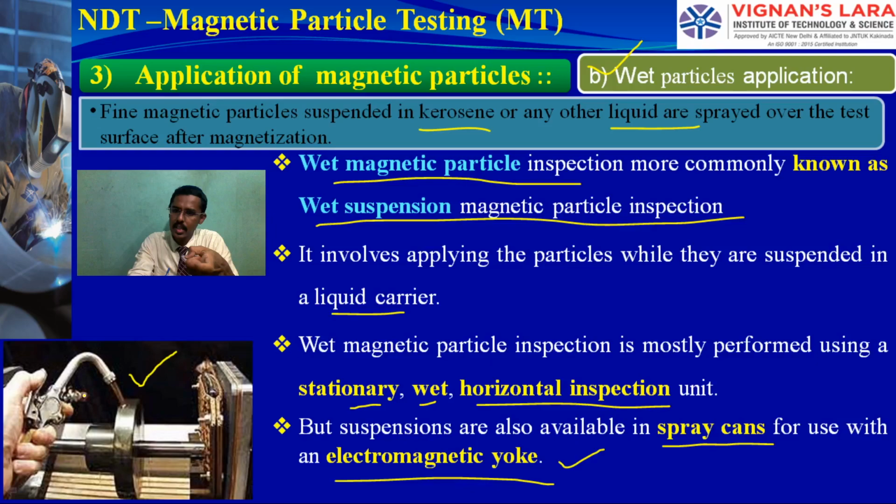The liquid carrier provides mobility to the particles for an extended period of time, which allows enough particles to float to even a small leakage and form visible indications.